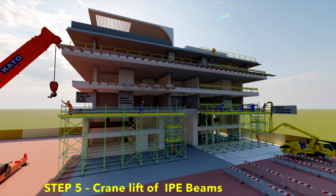Pay attention to the workers involved in the step. Are they positioned safely? Do they have the necessary personal protective equipment? How are they ensuring that they remain clear of the load and the crane's operational path? Reflect on the surrounding environment. What is happening below the area where the beams are being lifted? Are there measures in place to prevent unauthorized access to this zone during the lift?